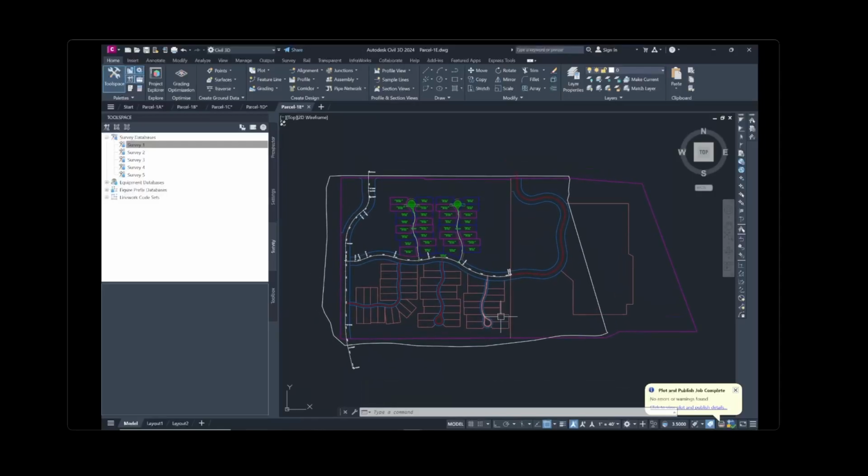This drawing contains 5 roads of a main west-east road. The 2 north and south side roads have centerline alignments, each of which created a parcel in the roadway and cul-de-sac center island. In the next few steps, you will convert the centerline of one of the southern side roads to an alignment and prevent it from forming parcels.